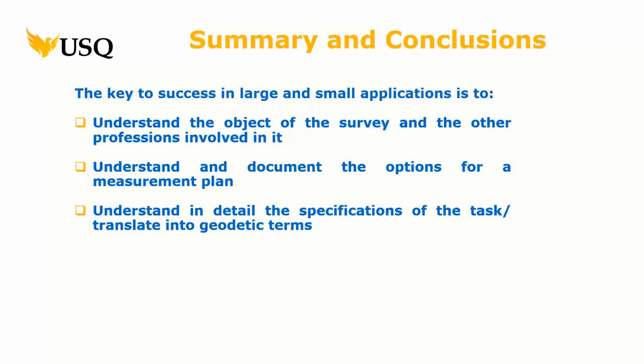So when someone says it's got a tolerance of this, right, in writing you find out what the specification for that is. So they're saying the beam placement structure over the holding down bolts has a tolerance of 10 millimetres, right? You're going to say, is that in all directions? Is it 95%, 99%, right? It doesn't matter if they don't understand. It's irrelevant, as long as they sign off on it. Because then you've got something to work to, right? That's a very important aspect.